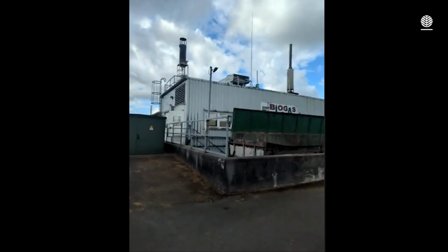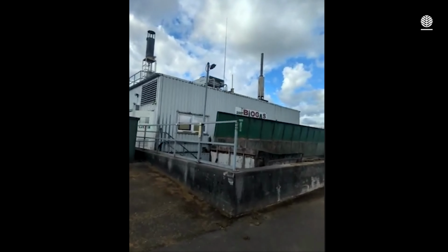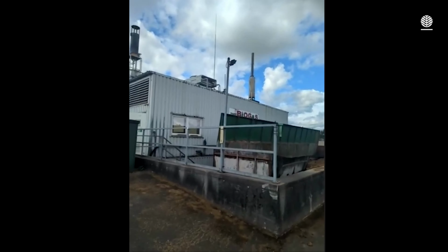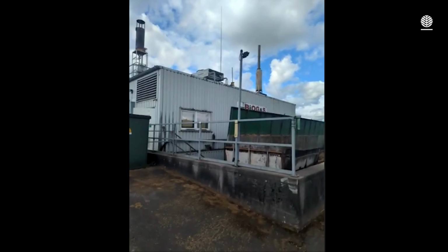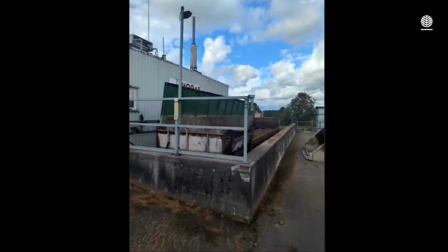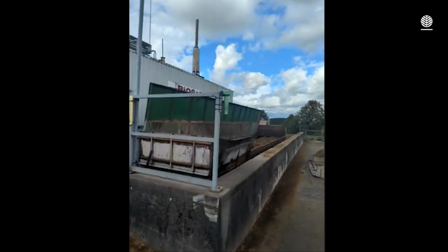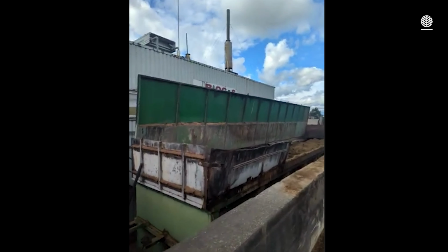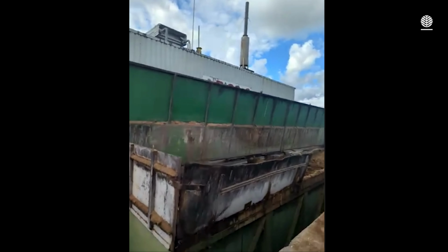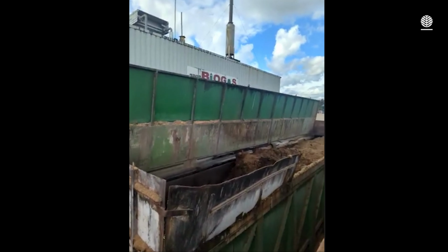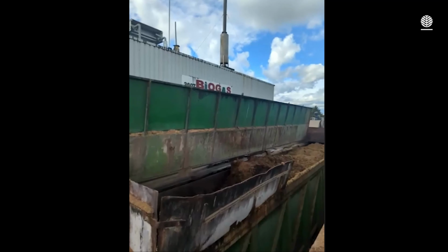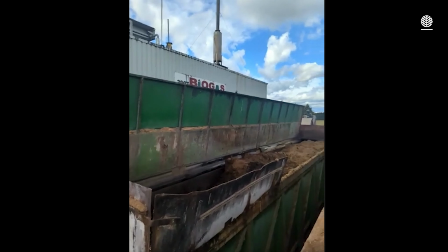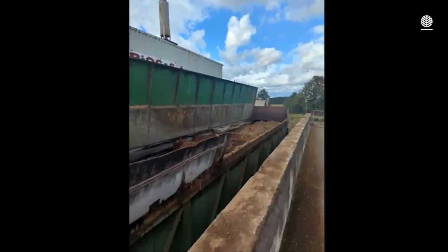So here you can see the dosing feeder. In former times, we decided to build a building around the dosing feeder, so it's easier to throw in the feedstock with the front end loader. So the operator is able to have a good view inside the dosing feeder. That's why we have a cellar or some ground floor building. And you can see it looks like 20 years old. We have corrosion because of the acids in the feedstock.